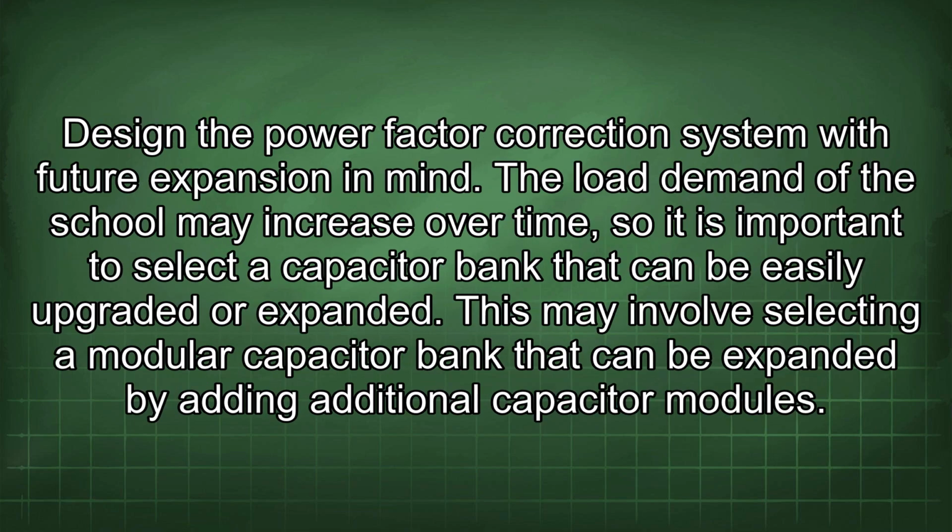Design the power factor correction system with future expansion in mind. The load demand of the school may increase over time, so it is important to select a capacitor bank that can be easily upgraded or expanded. This may involve selecting a modular capacitor bank that can be expanded by adding additional capacitor modules.